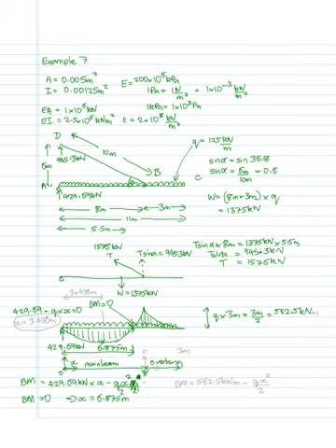So we've got the reaction minus the load caused by the UDL, and set that equal to 0, and then we will get that x is equal to 3.438 meters. So we're effectively saying that the maximum value there is going to occur at 3.438 meters.